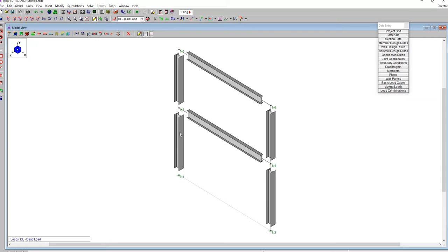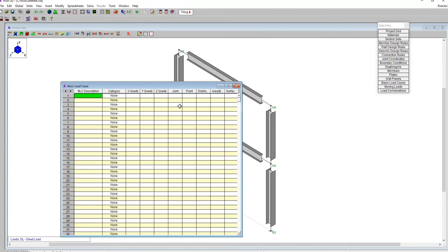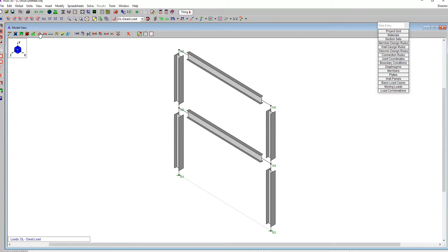Make sure that you choose the right ky and kz and then apply our loads. So loads are joint loads here. I'm going to apply a point joint load, but I have to say what load case that is before that. So we're going to go to the basic load cases. I'm going to label it as dead load, and the category is of course dead load. It's in the y direction, -1, and the same thing for the live load, LL. The category is live, and that's -1 for the direction. Okay, and then we're going to apply that.